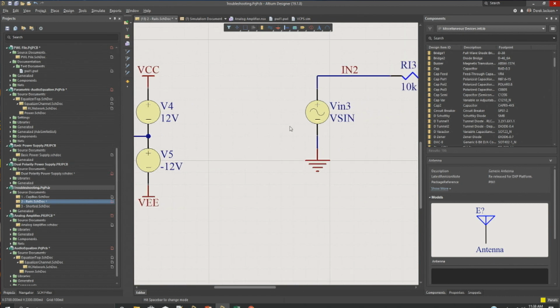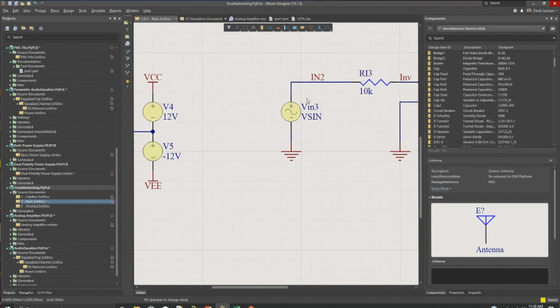Also, when you think about Kirchhoff's voltage and current laws, SPICE handles measurements a little bit differently, because it's looking at basically the current into pin 1 versus current out of pin 1. So when you're doing a current measurement, and you expect the current flow in one direction but it's negative, it could really just be the direction of current flowing in or out of that device. Sometimes just flipping the device around, if you're measuring current through it, will give you the right sign. So it's mainly when you're doing current measurements that SPICE can fool you sometimes.